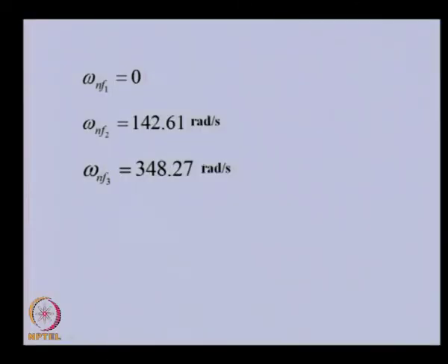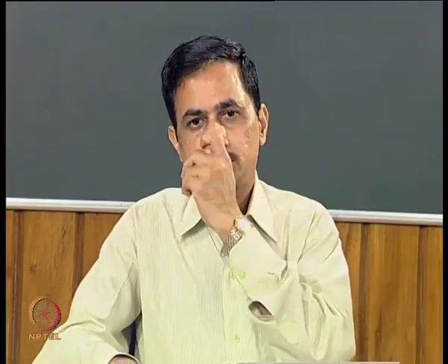In this case, because we considered the gear polar moment of inertia also, when we use the transfer matrix, we basically get a 3 degree of freedom system of this form, because this corresponds to the gear system. So, that is why we are getting 3 natural frequencies. One of them is 0 because of the free boundary condition. Okay. I will conclude now.